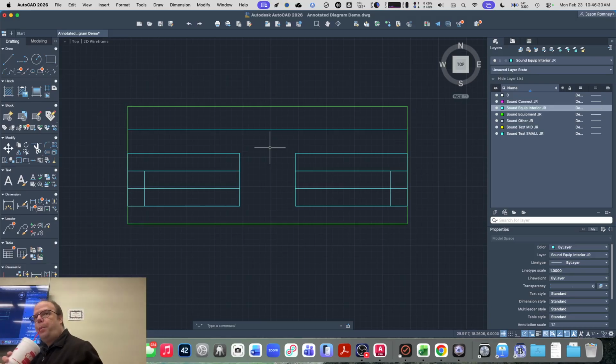Yeah. I'm having trouble coming down from the top to get exactly 2. It just puts a point anywhere. I'm not quite sure. Do you have the object snap tracking turned on? I think so. I'm trying to find it because I'm in Windows. Yeah, looks like you. Okay, so pull up the tracking.